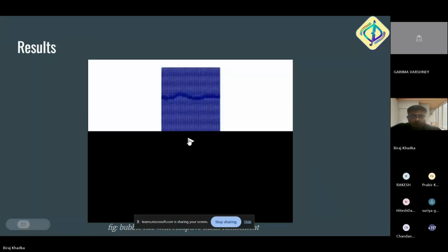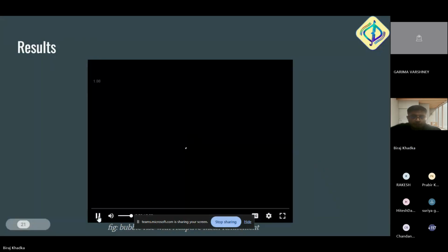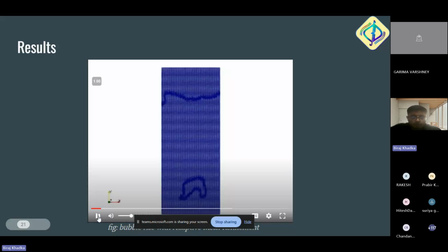So this is a dynamic mesh. As you can see, at every iteration, at the interface between 0.1 and 0.9, there is a refinement going on. And also here you can see it at the interface. So that is the domain of interest in multiphase flows. It is complicated to model. So AMR saves our time and increases our efficiency.